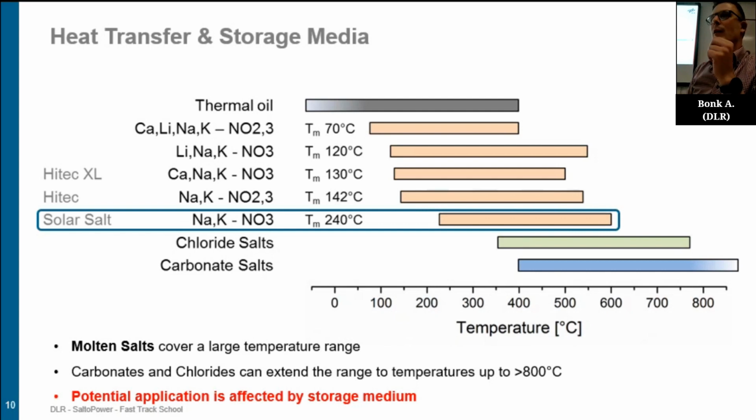That's something that's making experimental design extremely challenging, which is why when people enter laboratory scale experiments for the first time, they typically destroy their furnaces. That's the first instance they do. So they put a crucible into a furnace, and after 1,000 hours, they take out the crucible. The salt is gone, completely gone, because it's either evaporated or it's creeping into all the insulation, into the electric heaters, and then your furnace is destroyed. You repeat the experiment and try to understand what happened. That's one side. That's the experimental approach.